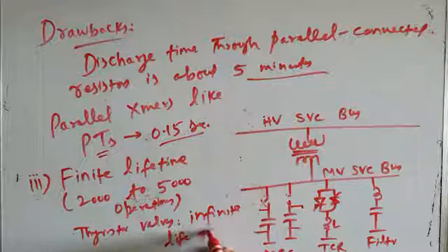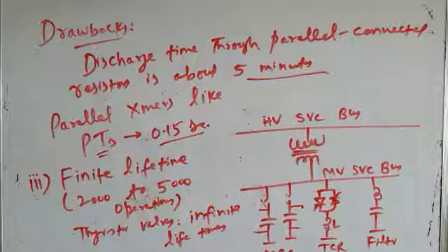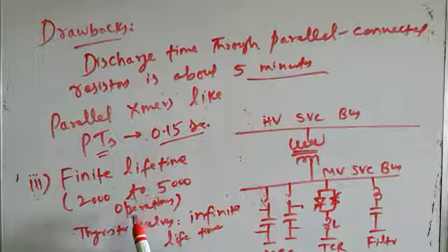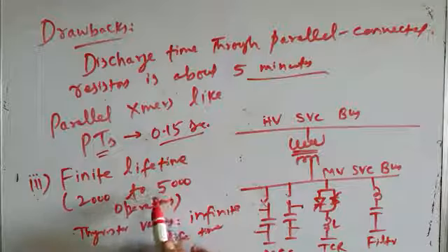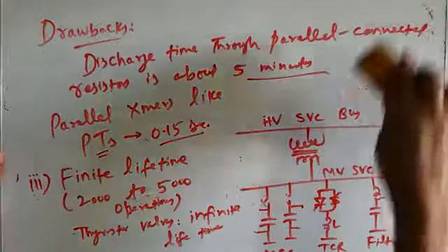Therefore, in TSC, TCR, SVC, we are using thyristor valves as switches. They have infinite lifetime. And on the other hand, in MSC, TCR, SVC, we are using mechanical switches, and mechanical switches have finite lifetime. This finite lifetime involves 2000 to 5000 operations.